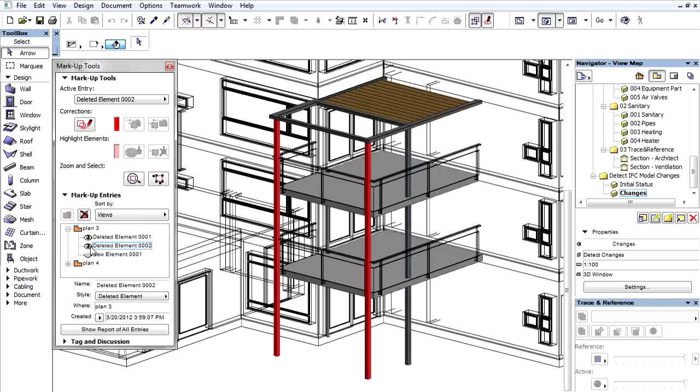It collects the detected changes grouped by status and different colors. The geometric and position changes are displayed as modified elements in pairs. The new and deleted elements are also highlighted with different colors. In this example, the solar shading system of this balcony part is modified, reduced, so two columns were deleted, one new column was added, and the roof size was modified by the structural engineer. Architects can accept or reject the changes suggested by the structural engineer in the architectural and/or referenced model environment.